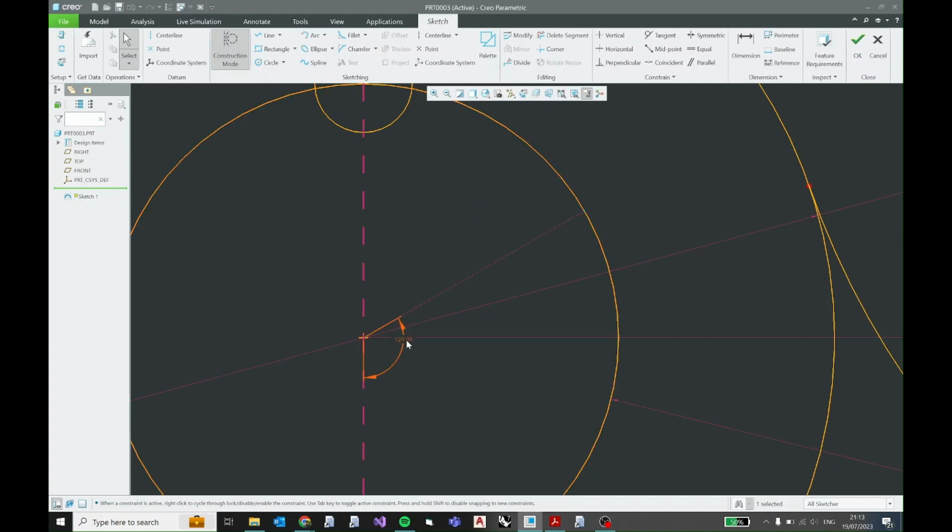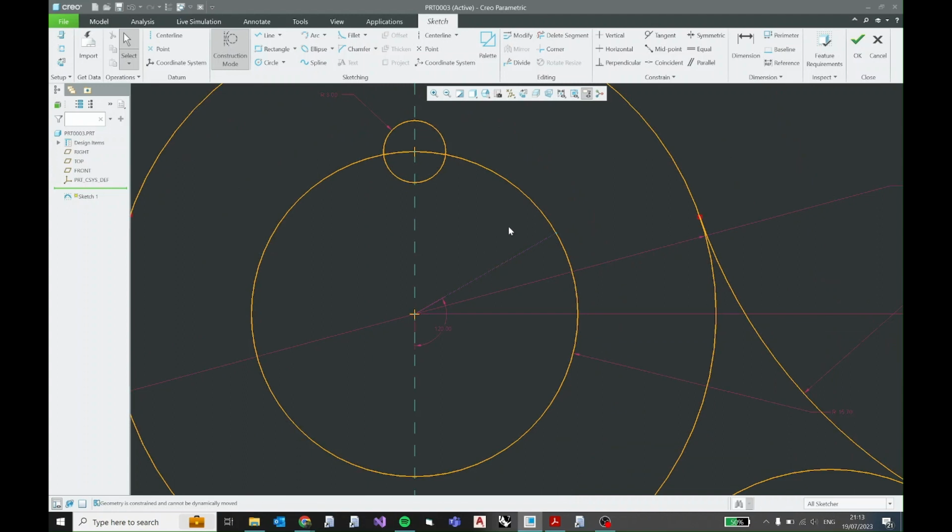So there's a little bit of math as well, but not a lot, so you don't have to worry. So you can lock this, so it is fully constrained now. So I don't have to make all 4 different construction lines, because I'm going to be using the mirror command as well in this. So I'm going to press escape again, turn off the construction mode, otherwise it's just going to keep on making construction circles. Perfect. And this is a radius of 3.0.